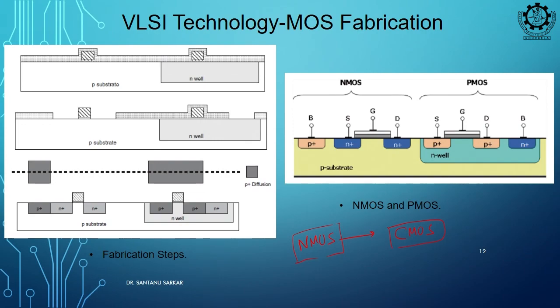Now, on top of this wafer, so this is your wafer P, on top of this P you will be doping a region which will be N, getting my point. Then on this N you need a contact connection, right. This will make a source, this will make a drain. So, you need some metal deposition, right. This metal will behave like an ohmic contact, right. You need some connection.